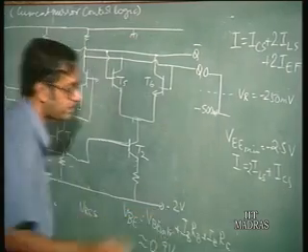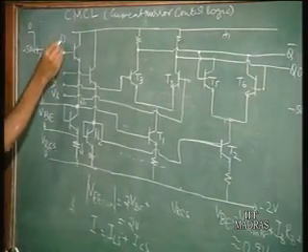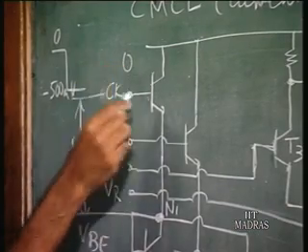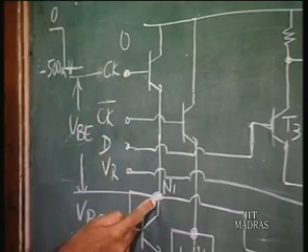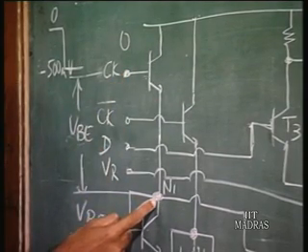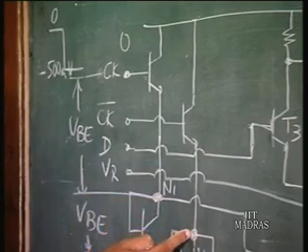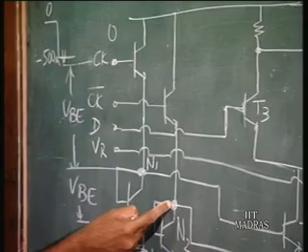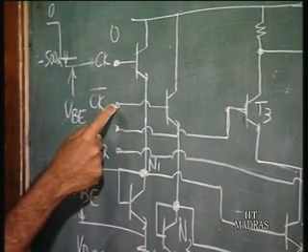And the input voltage is clock and clock bar, 0 and minus 500 millivolts. So, if it is 0 at node N1, and if we assume VB is 0.9 volts, N1 is going to be 1.1 volts, whereas N2 is going to be minus 1.4 volts, isn't it, with minus 0.5 at the clock bar input.